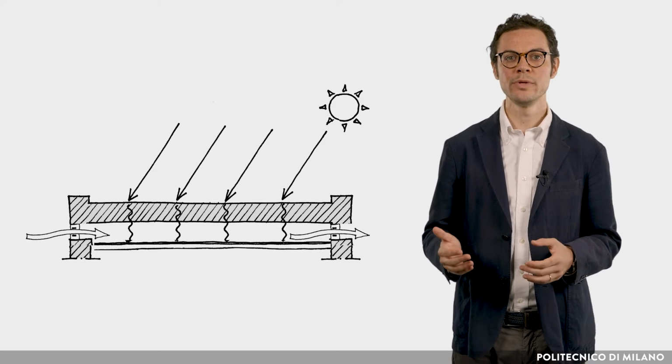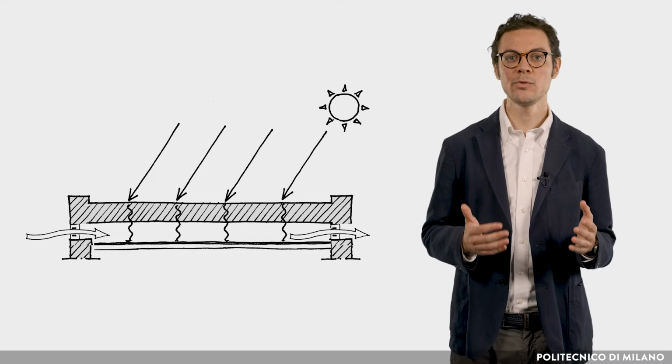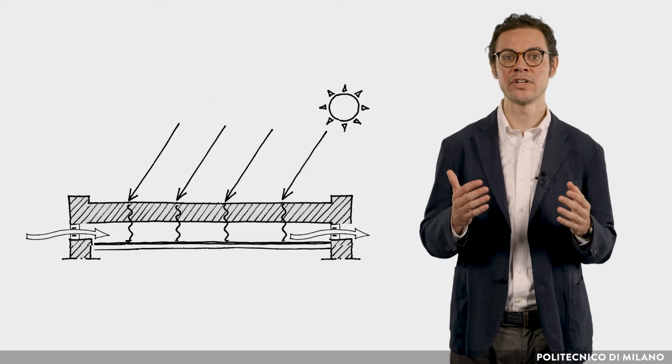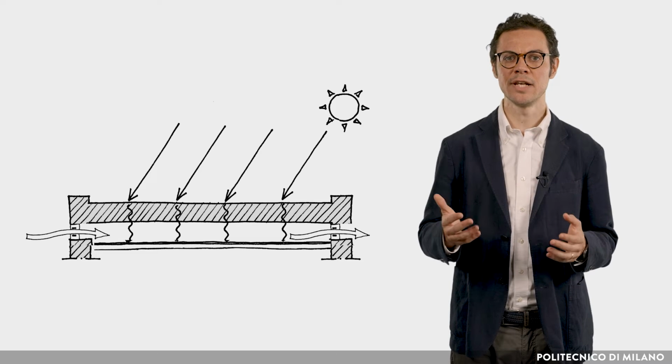Regarding the building elements, note that roofs should preferably be made of heavyweight materials and high reflectivity coatings and should be ventilated.